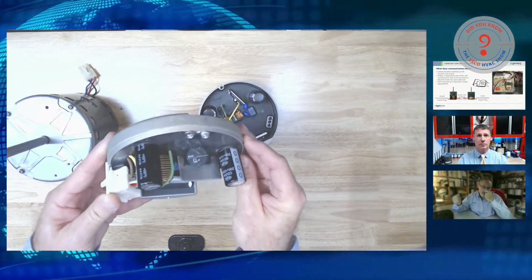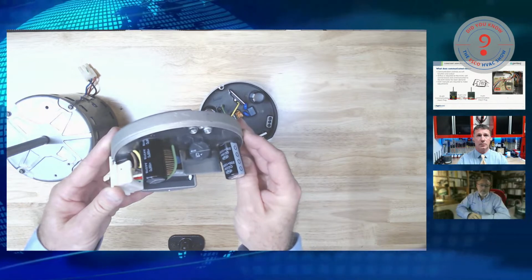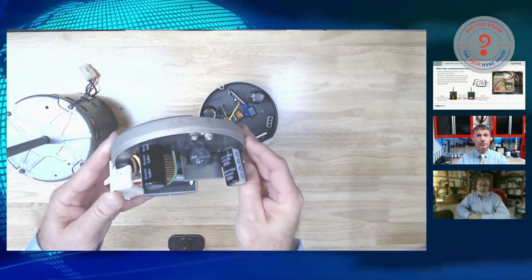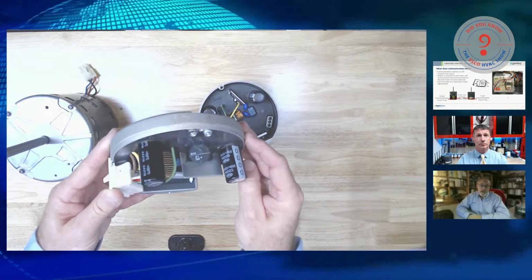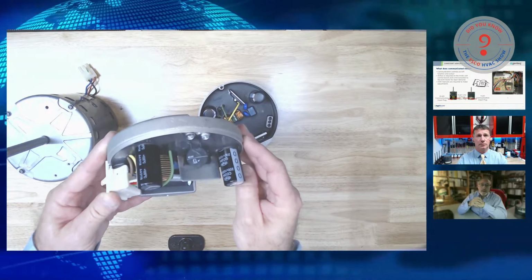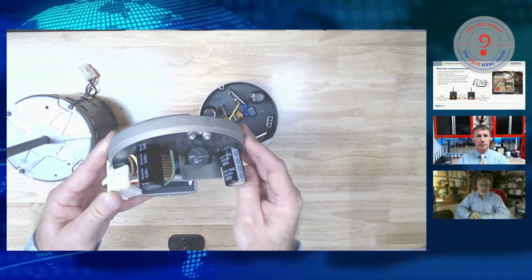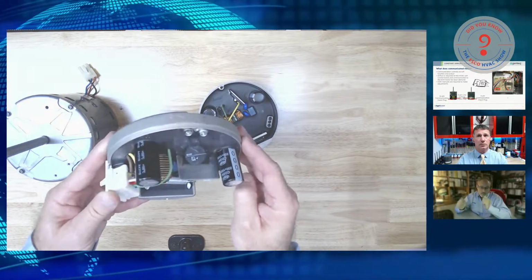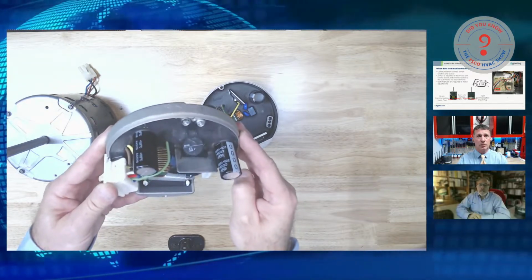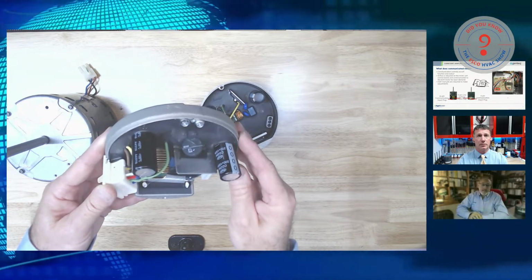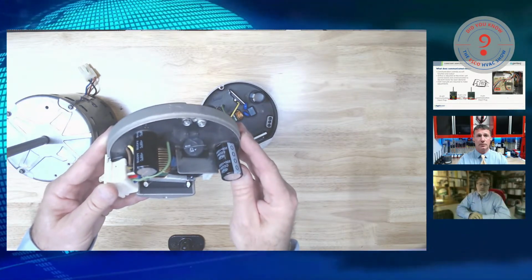Right there, you've got a half-horse module. That's 2,000 mics a cap that are going to want to charge up all at once. So that NTC inrush thermistor's job is just to slow that current down for a millisecond so that we don't pop the main breaker every time somebody resets the power or takes the door on and off. Sure.